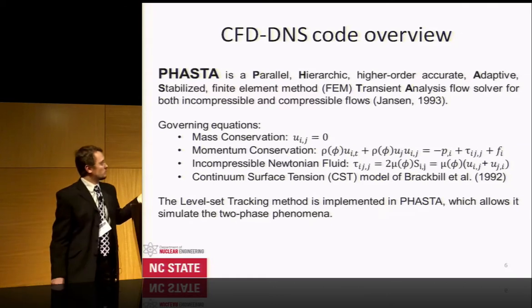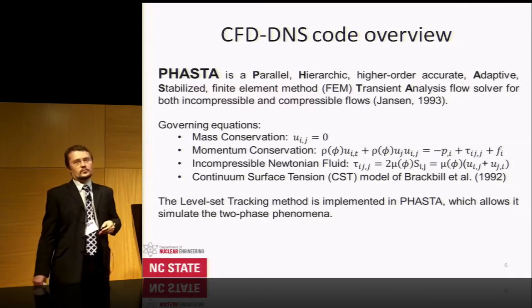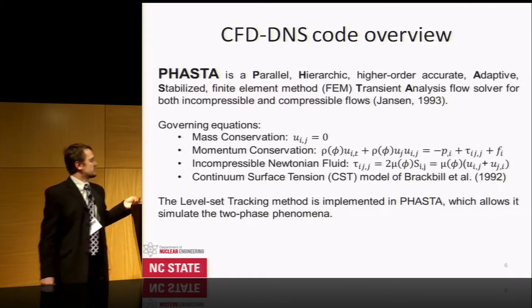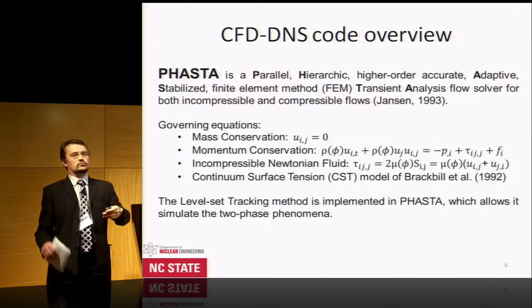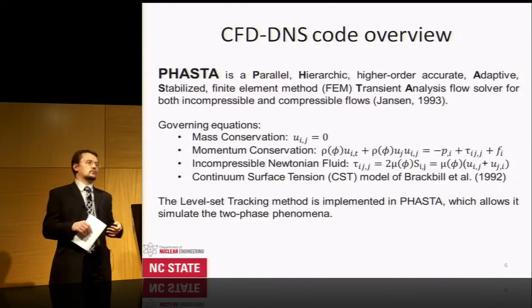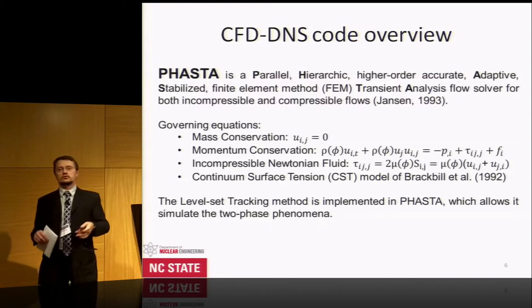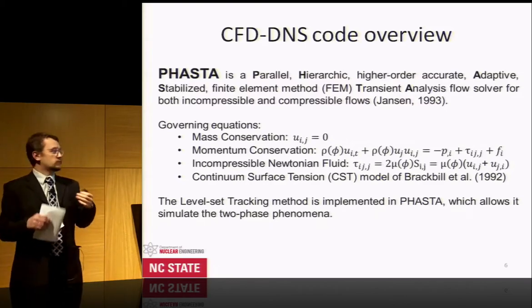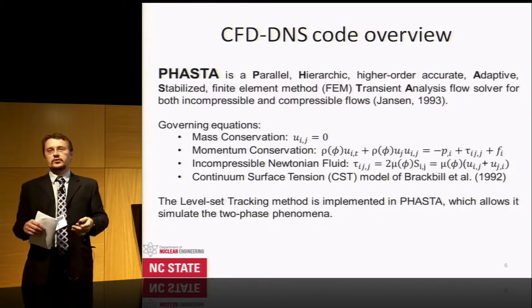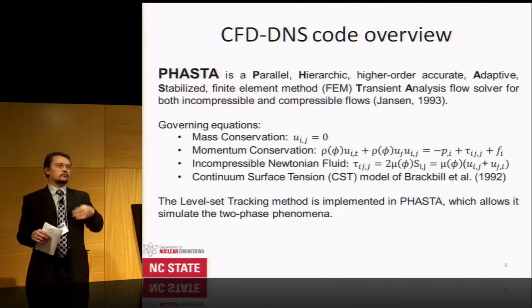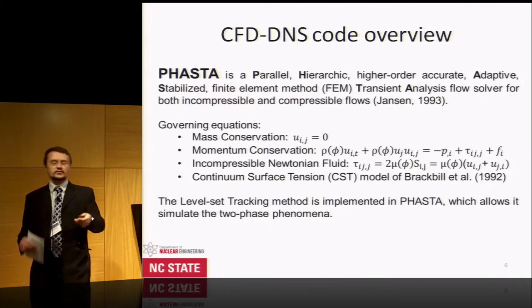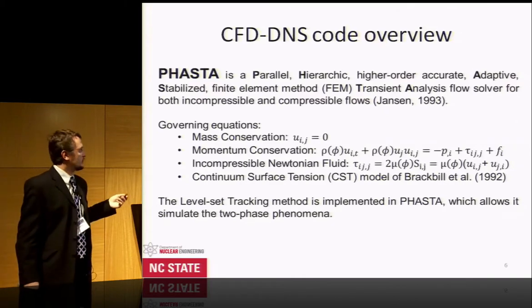I think this is the only equation, or almost the only equations, I'll show. But bottom line, we solve mass conservation and momentum conservation for the fluid, and we fully resolve the turbulence. So we have very little closure loss and very little uncertainty, so sometimes you can call it virtual experiments. But in order to achieve that, of course, you have to have a lot of mesh, and a lot of mesh is expensive. Hence, HPC again.